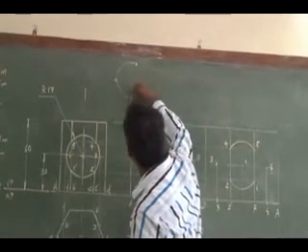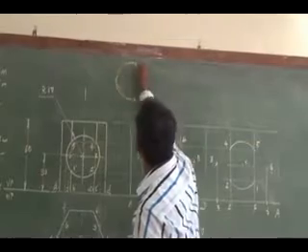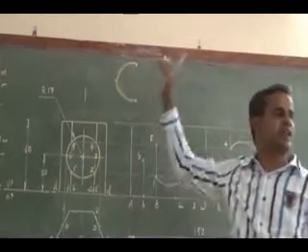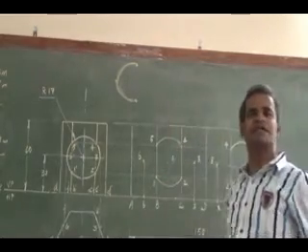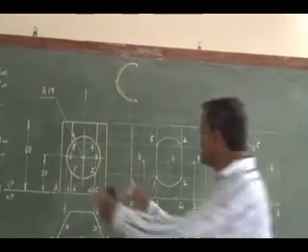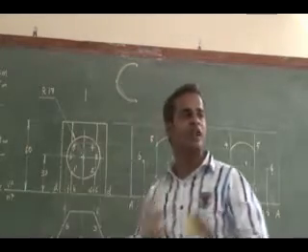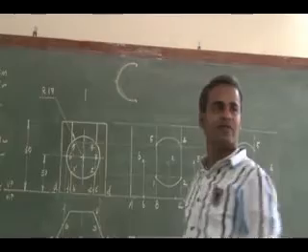Smoothly, the circle you have to draw it, tangentially it has to connect. It won't have a radius of 17. If it falls on the flat face, it will have a 17 mm radius. Since this portion 342, that is 561, falls on a slant face in my front view, it will have a different radius.